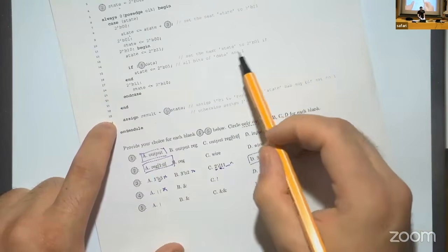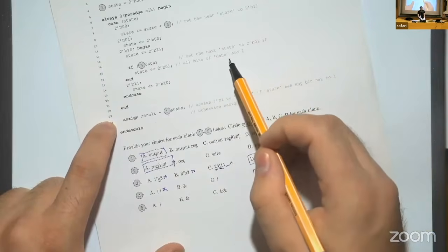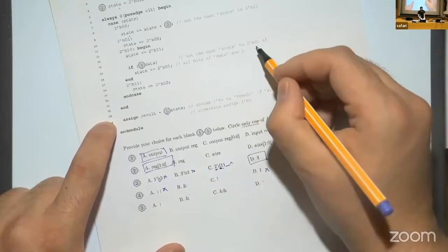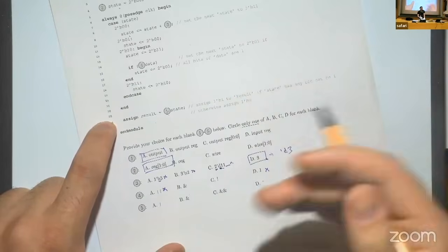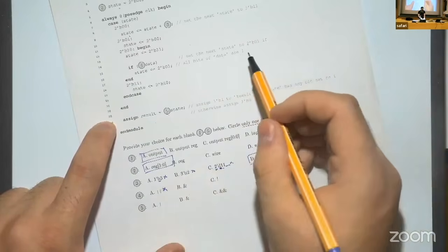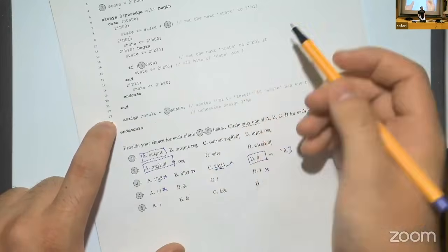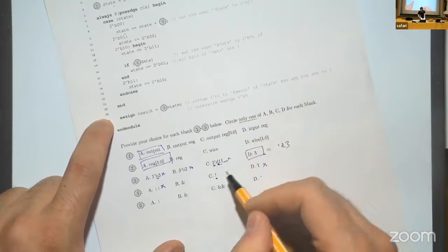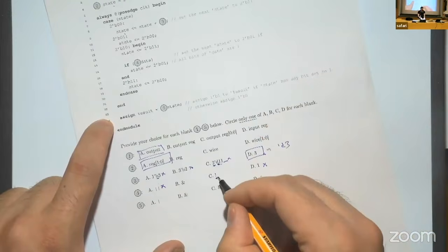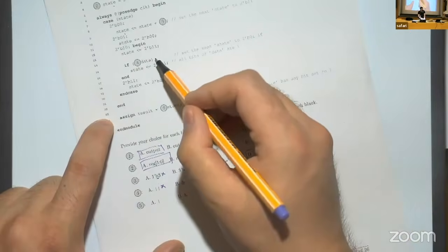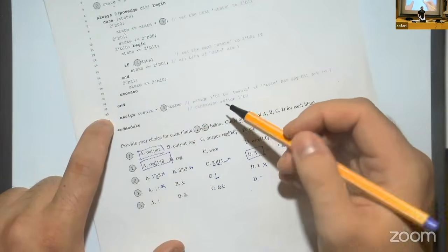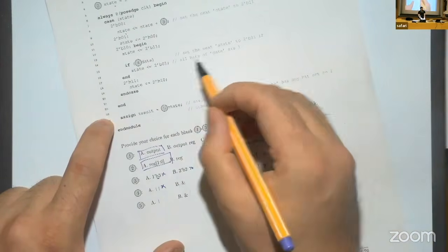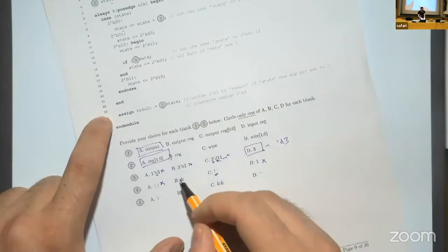We know that it says if all bits of data are 1, which means that we have to perform AND reduction, and then we will understand that all the bits are 1, right? If we use C, it's a logical negation. We have 8 bits of data. It will get the least significant bit, and that's why you won't satisfy this constraint. So the correct answer is B.